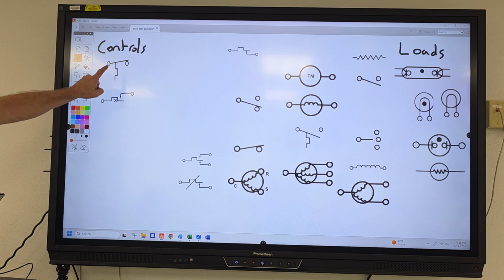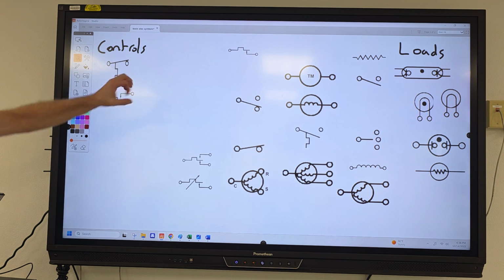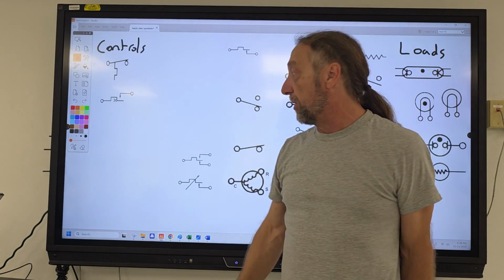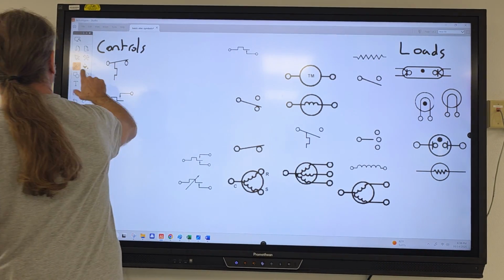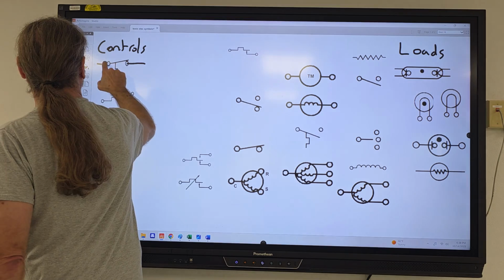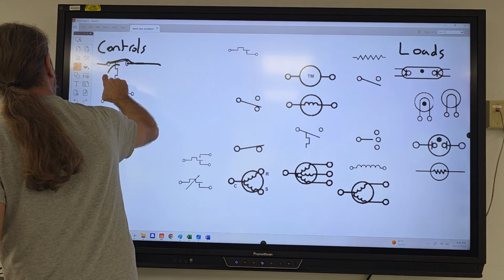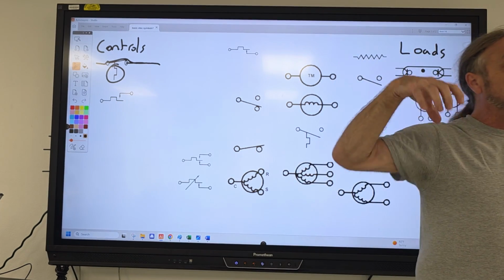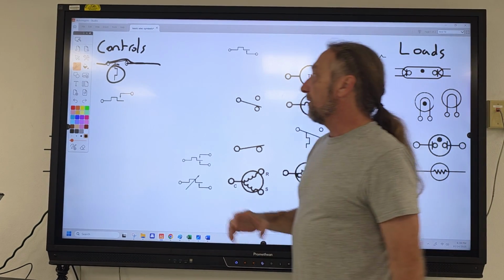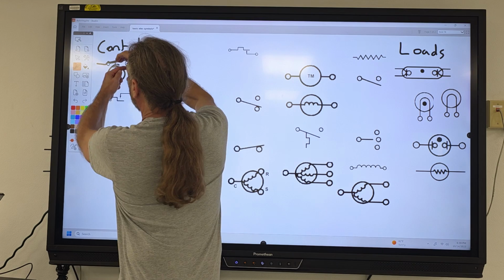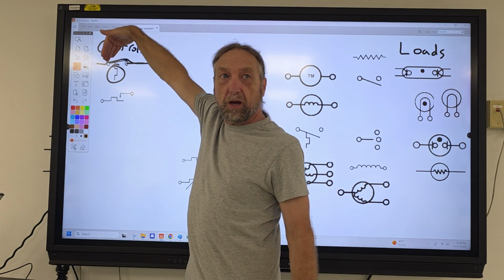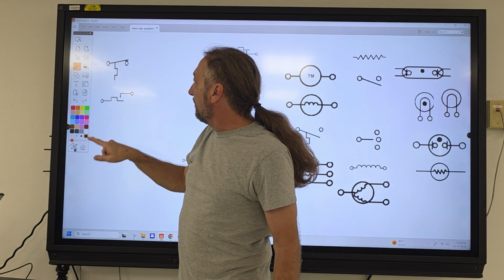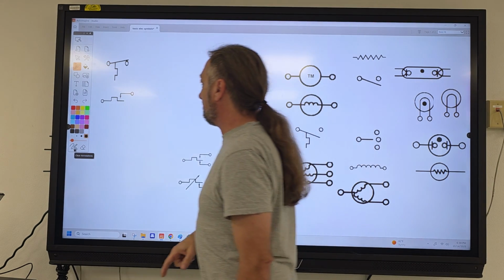The top one. Power goes in and out through those two dots. Those little circles are telling you where the wires connect to the part. And power comes in, goes through this little switch and out. This piece is telling me that's like the sensor of the heat. Okay? So if it gets hot, it pushes it and opens the switch up. And then it closes back again.